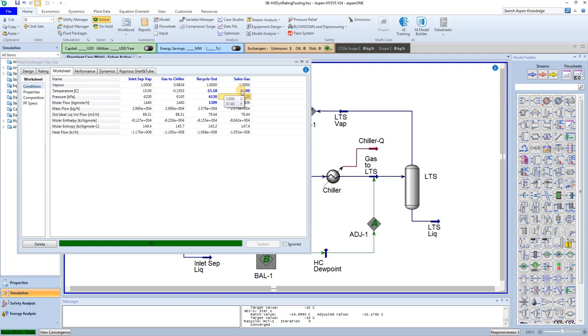The gas-gas heat exchanger is now defined and calculated based upon a desired process condition. The model also contains the stream compositions and physical properties that match up with these conditions. It is this data, conditions, compositions, physical properties, etc., that are required for a rigorous heat exchanger design calculation. So at this point, we can transition on to the rigorous Aspen EDR environment and make use of Aspen Shell and Tube Exchanger.